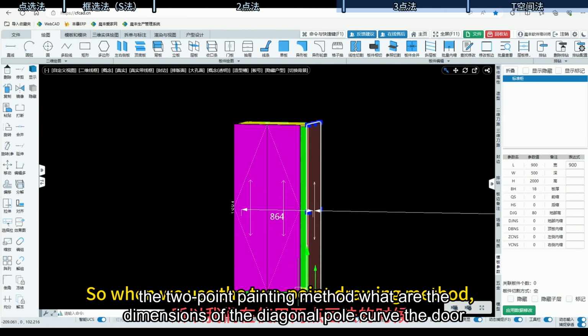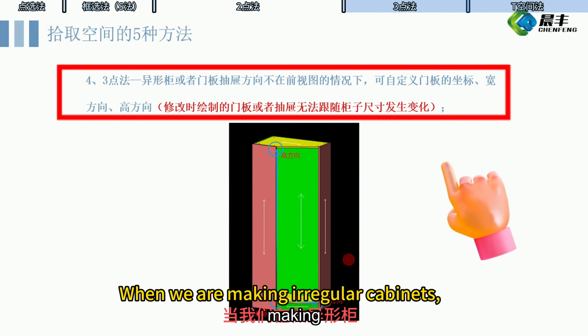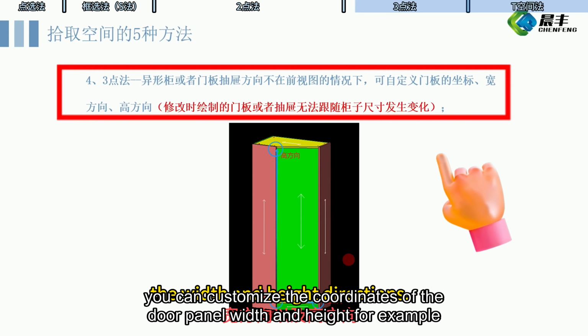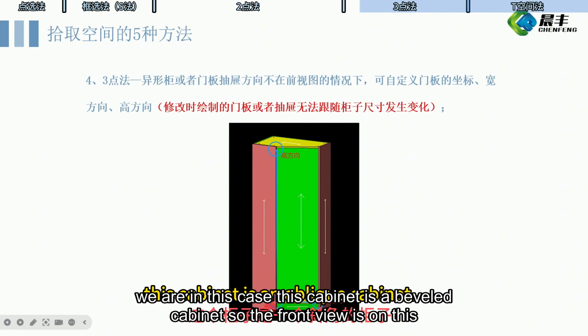So when we use the two-point painting method, the dimensions of the door panel or cabinet we drew are just fixed. The fourth method is the three-point method, when we are making a line of cabinets, or door panel drawer, when the direction is not in the front view. Use this method. You can customize the coordinates of the door panel, width and height. For example, like our case, this cabinet is a beveled cabinet, so the front view is on this side.